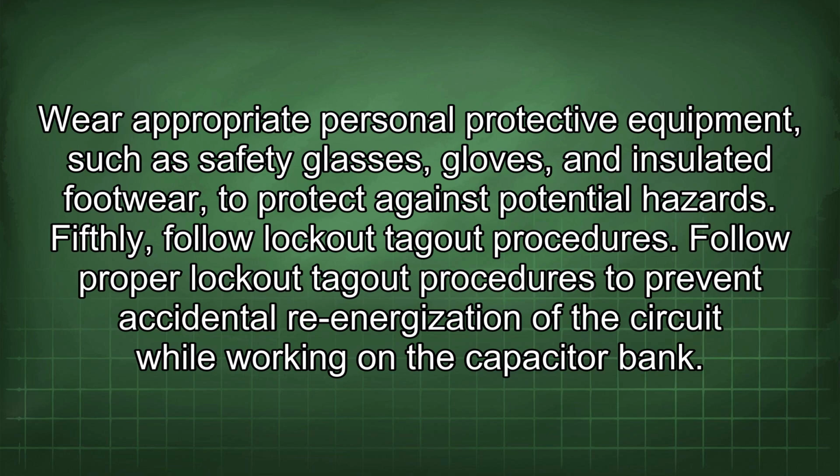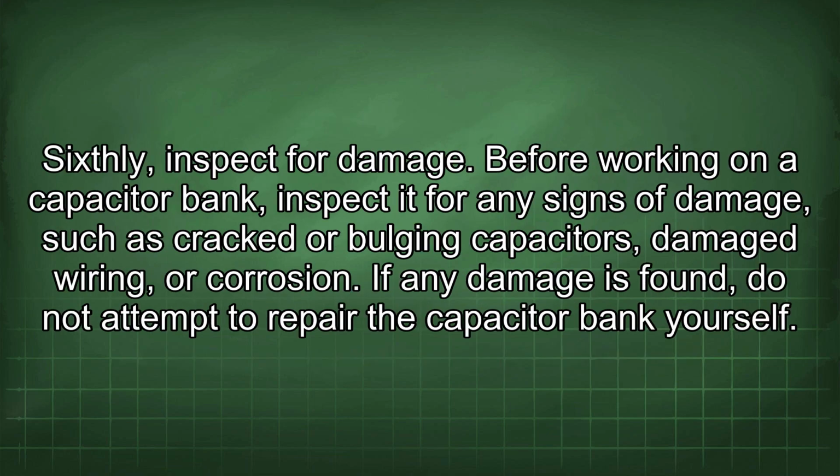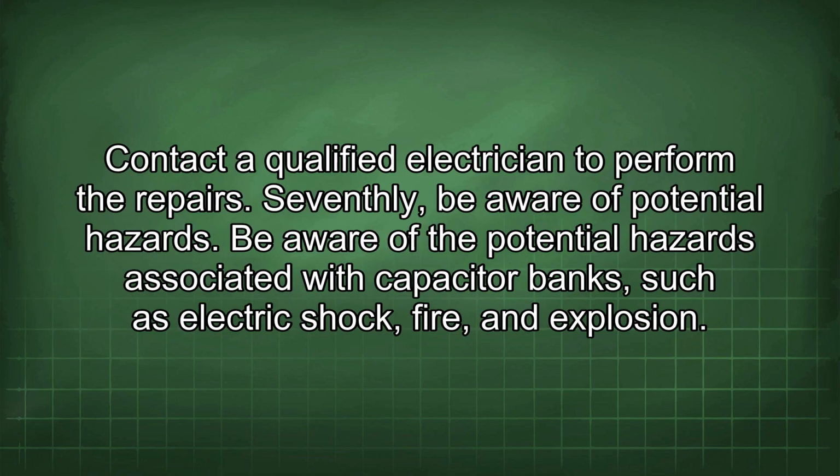Fifthly, follow lockout-tagout procedures. Follow proper lockout-tagout procedures to prevent accidental re-energization of the circuit while working on the capacitor bank. Sixthly, inspect for damage. Before working on a capacitor bank, inspect it for any signs of damage, such as cracked or bulging capacitors, damaged wiring, or corrosion. If any damage is found, do not attempt to repair the capacitor bank yourself. Contact a qualified electrician to perform the repairs.